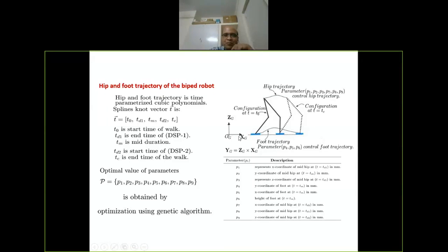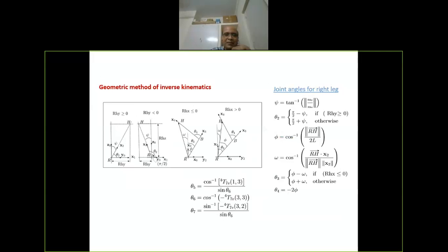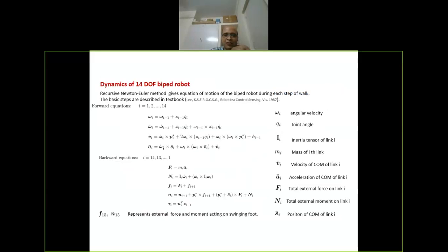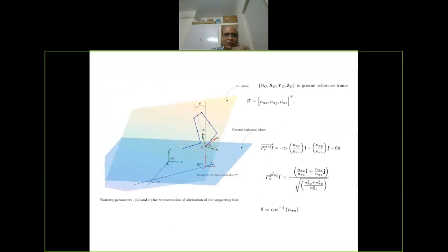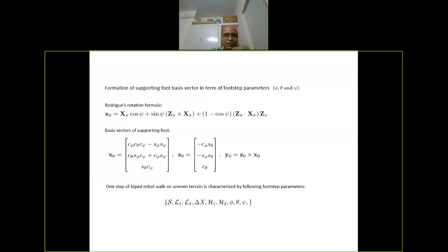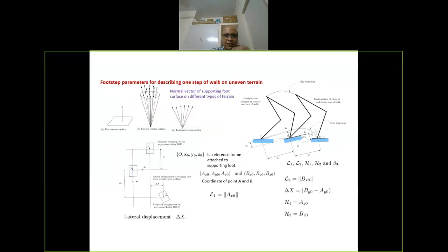So what we do is for each of these combinations, we get a number of optimal parameters, which are the inclination upward, inclination downward, angle of turn right, angle of turn left, and the step length. So these are all variables. We discretize it into 5 millimeter steps, and then for each of these, we find what is the optimal trajectory. Okay? So basically we do the dynamics, what I just explained. We find the energy optimal trajectories. This is how it is done for an upward inclined ground.